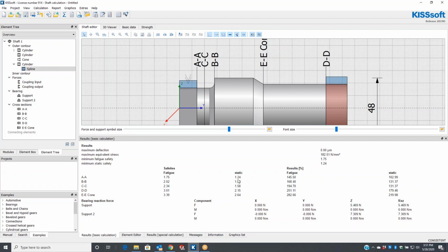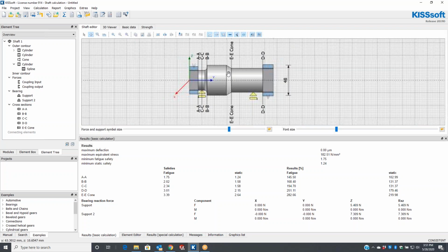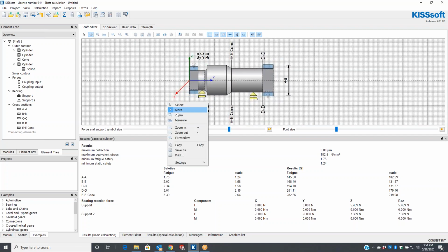Okay. So this is a quick way, if you have cones on your shaft and you need to calculate that in a rough or quick manner, it's an easy way to define what this notch factor is. And you can see the effect, and you can play with this pretty quick.